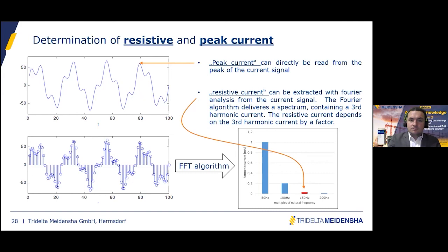Maybe also local hotspots produced by one failed block or two failed zinc oxide blocks, and this gives you a value. But continuous condition monitoring doesn't seem to be possible with thermal imaging.